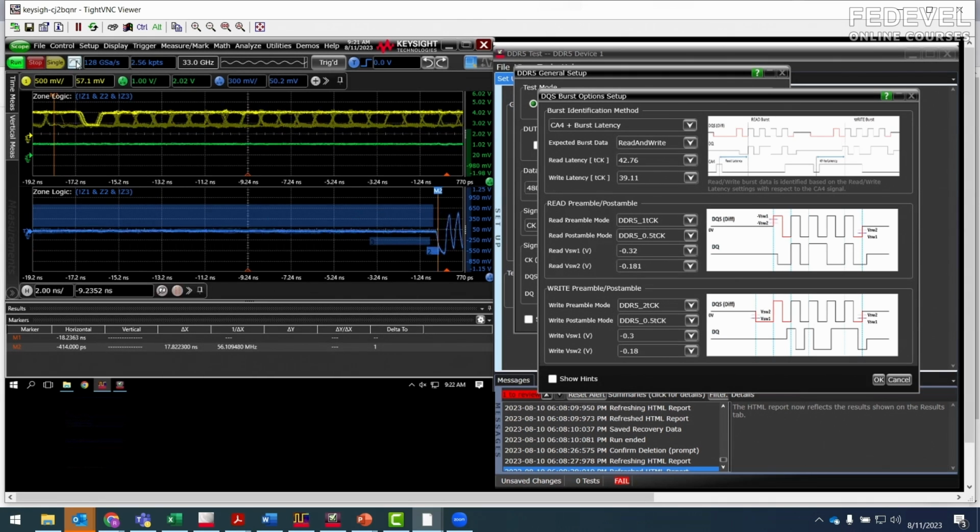Yes, I can see it. Okay, there we go. Now it's always low, and there's our latency. It's a little bit different. Instead of 17.6 or whatever it was, now it's 16.8. And that corresponds to 39.11, if I convert the clock cycle that I have.